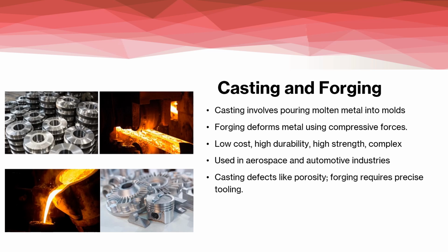On the other hand, in forging, metal is heated until it's malleable and is then deformed into the shape that is needed using immense mechanical force. These materials are highly durable, meaning long-lasting and can resist wear. They have great tensile strength, so they don't buckle or fracture. These processes are mainly used in aerospace industry and automotive industries due to their resulting properties such as longitudinal grain flow across metal surfaces, making it stronger and resistant to impact.